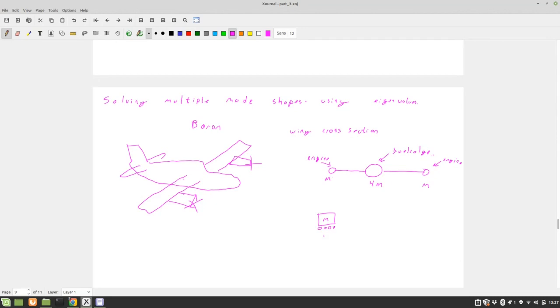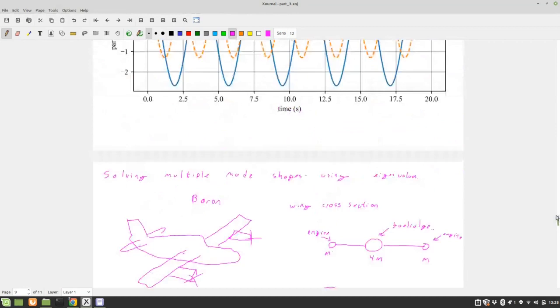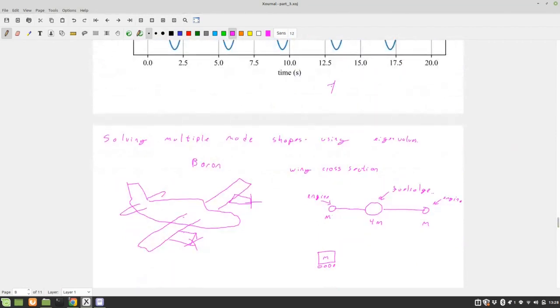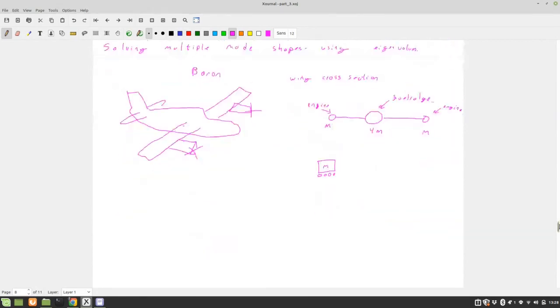And maybe a spring. Okay, but we can also, remember when we had a cantilever beam, right? And we converted a cantilever beam to something that looked like a point mass to this. Remember when we did that? Well, maybe we should just do that here, right? Let's try that. So let's just put 3 of those in.